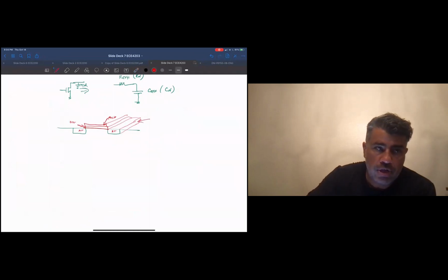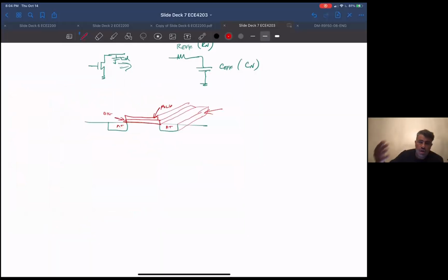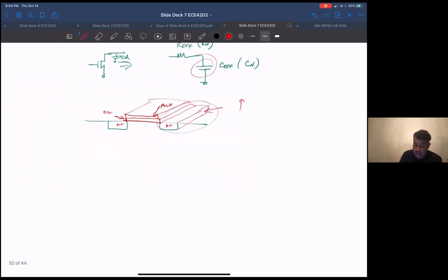It's a reverse bias junction. So as the voltage goes up, the capacitance shrinks and vice versa. So it's not really a constant capacitance. It's still kind of an estimate. What happens is SPICE is actually recalculating this capacitance for every voltage step. So anyway, you have that value.